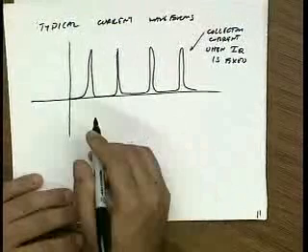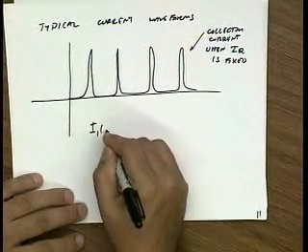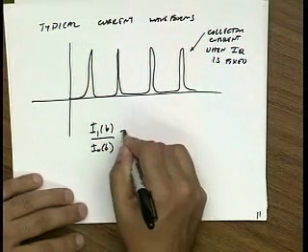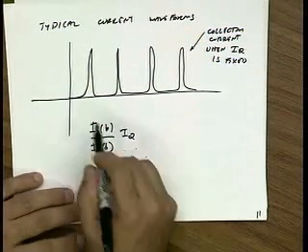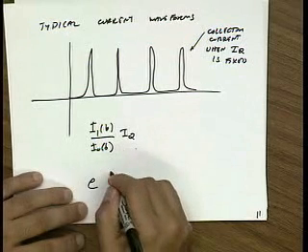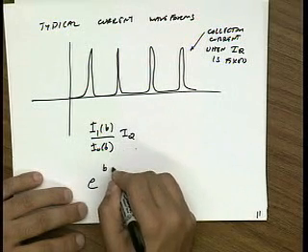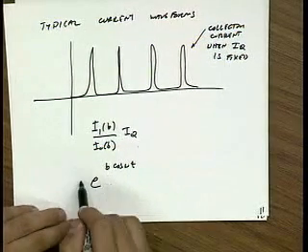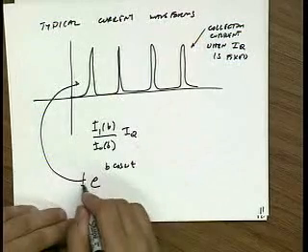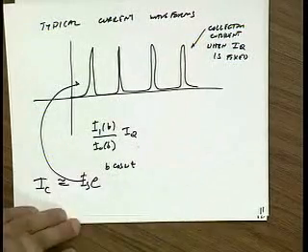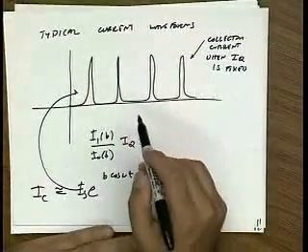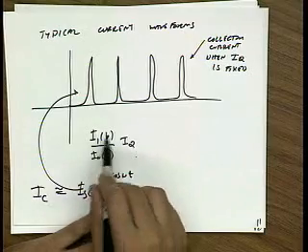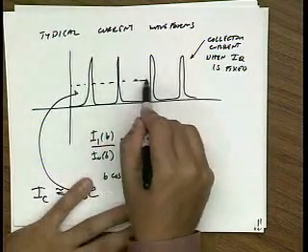So in fact, go into Mathematica and plot I1B, I0B, IQ, and actually it's easier just to plot B cosine omega t and make B very large, right? And this is what the collector current looks like. It's becoming very bursty, and so if you plot it for large B versus if you plot it for the bias current being limited, you get different waveforms, okay?